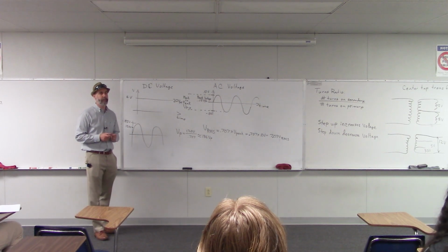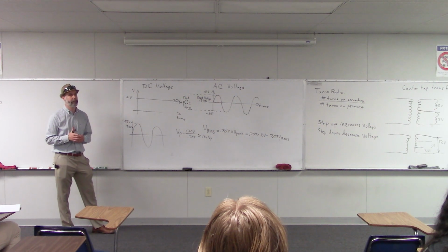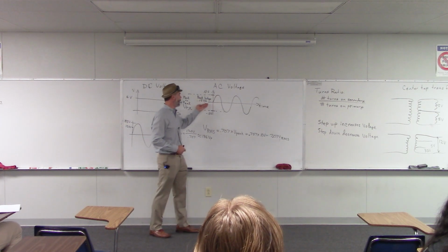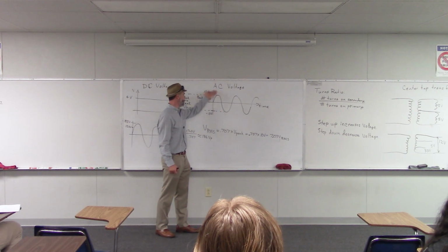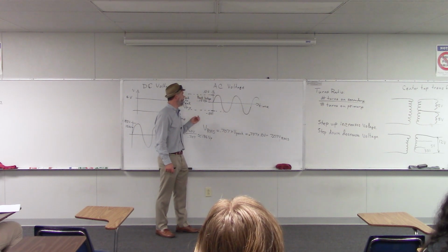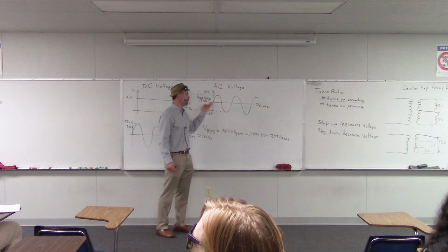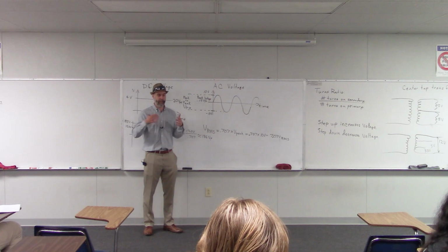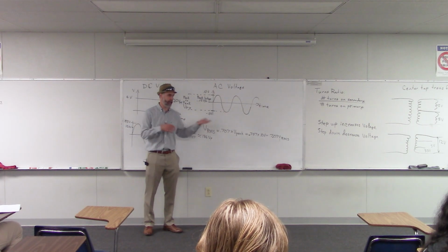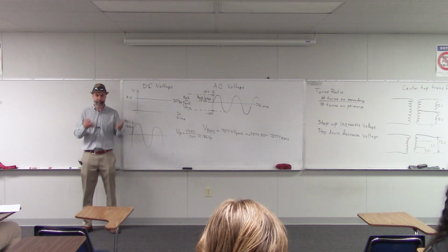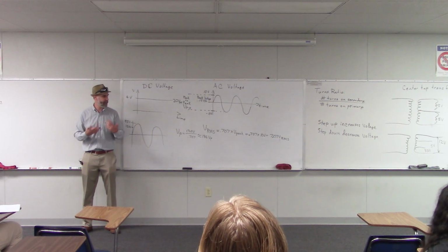The 0.707 is just the relative amount of power that you need in DC compared to AC? So yeah, what it means is if you put an AC signal into a heater that's 10 volts peak, you would need about a 7.07 volt DC signal to match the heat that's coming out of that heater. Okay. So yeah, it's kind of a way of comparing apples and oranges that makes them somewhat similar.